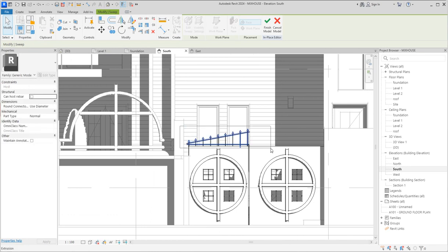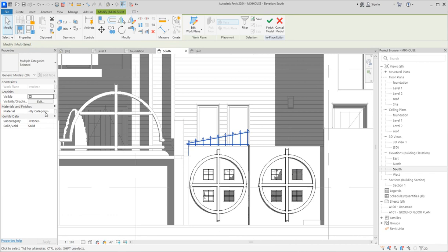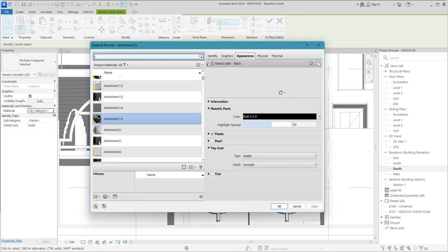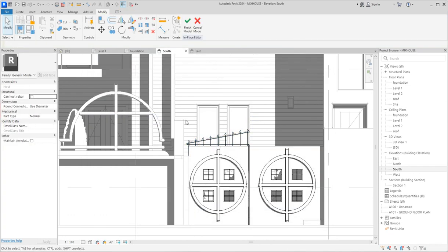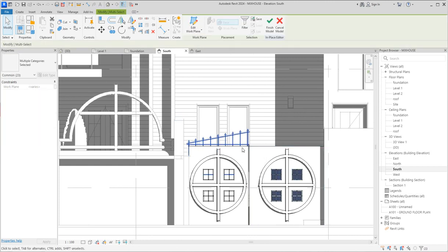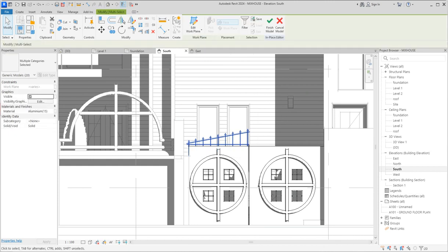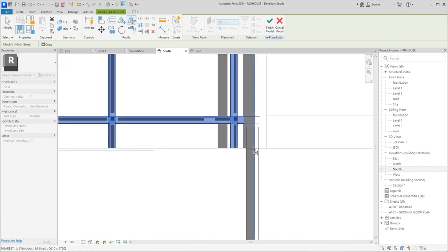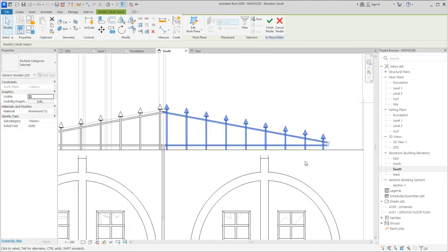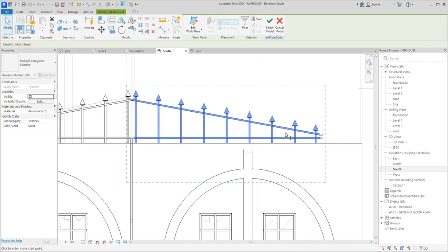So select this one and change the material to your taste. So category, and select the material again. Here after you have done it, you can now mirror it to fix up with what you have been doing with the opposite side. So click here and say mirror. Mirror. Good. So mirror is set. You can decide to now adjust this, move this to the base.